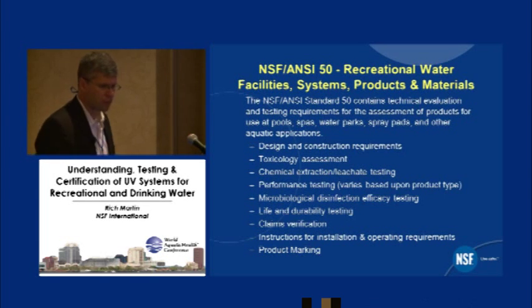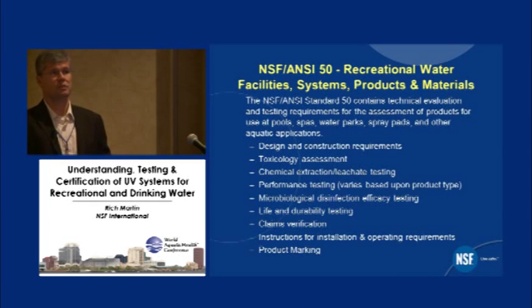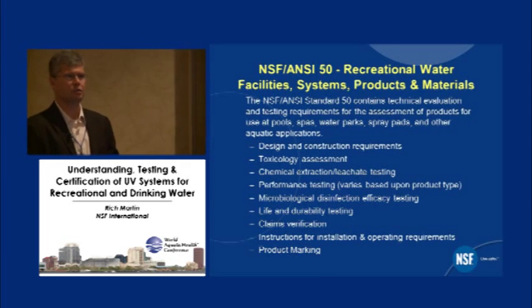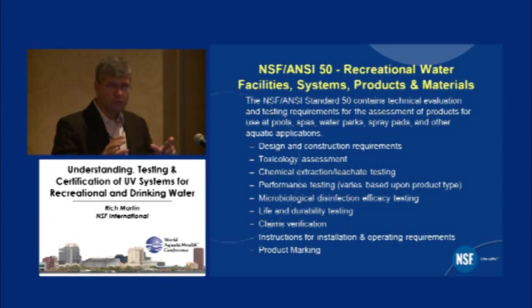So I mentioned NSF Standard 50, and some of you are familiar with that, but really that criteria is like a 3D evaluation of a product. Standard 50 has health effects criteria, corrosion resistance, design criteria. It also has microbiological disinfection efficacy requirements, what I'll call other gross physical performance requirements related to burst pressure testing and things of that nature, but also incorporates claims validation and requirements for the installation and operation manual. So there's a great deal of things that are specified.